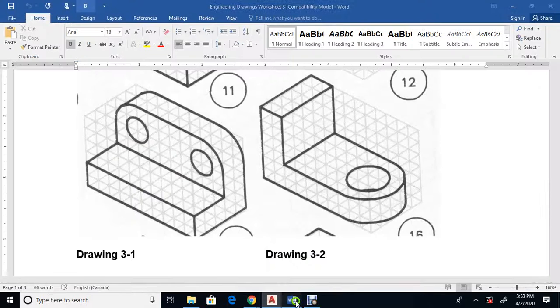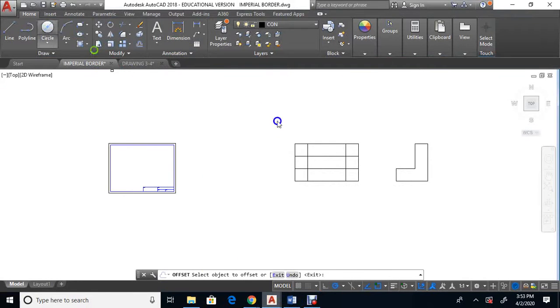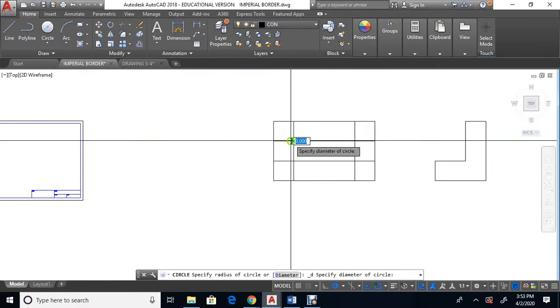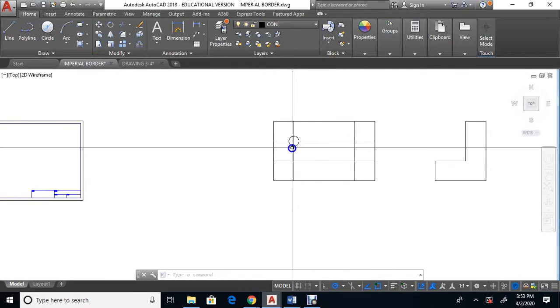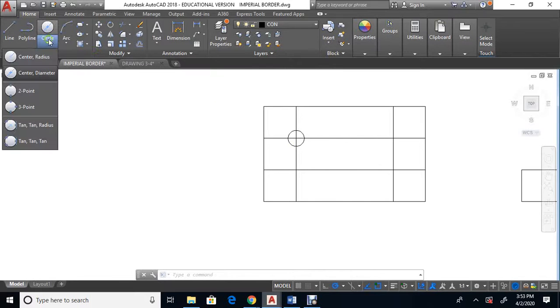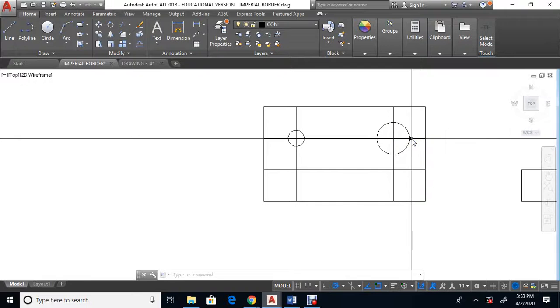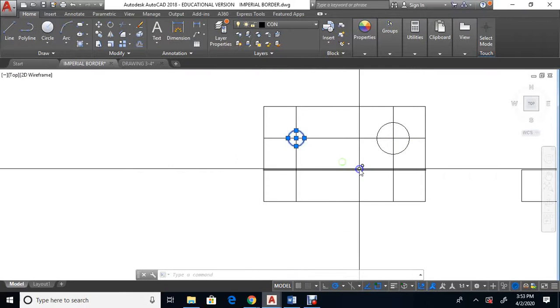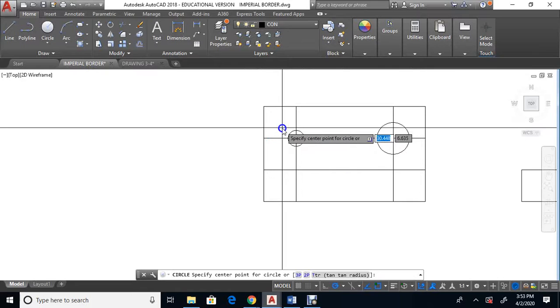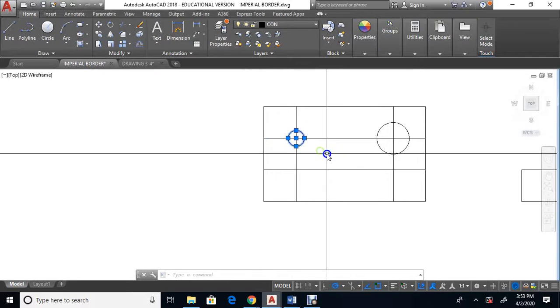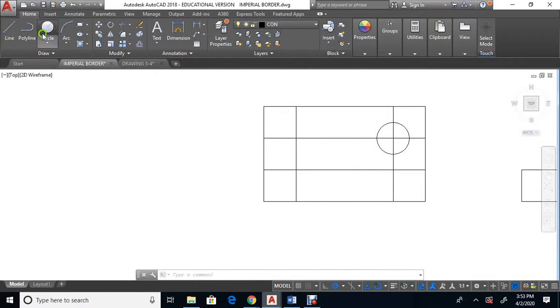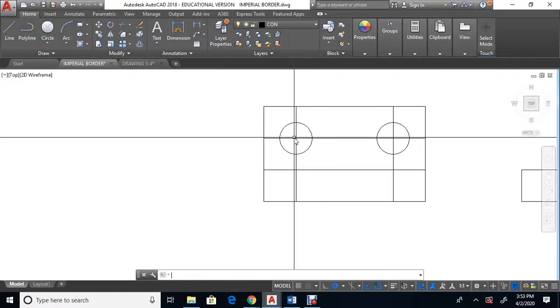Then I'm going to go back, and I'm going to see, oh, it's a 2 diameter, 1 radius hole. So 1 this way. So let's go back to the AutoCAD drawing. And now at this point, I'm going to do a circle here with a 1 radius. Oh, let's make sure I got the right circle. Circle. So I'll click here, and I'll pick 1, enter. That one looked a little too small. So I'll repeat the circle. Oh, didn't want to erase that. Let's do that again. There, delete. Go circle, pick here, and have that same 1 radius.